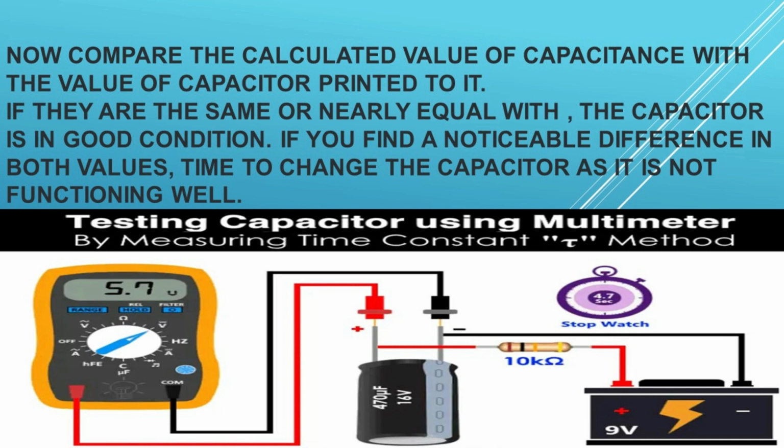Make sure to connect the positive, red, lead of the voltage source to the positive lead, long, of the capacitor and negative to negative. If you are not sure or unable to find the proper leads, here is the tutorial on how to find the negative and positive terminal of a capacitor.